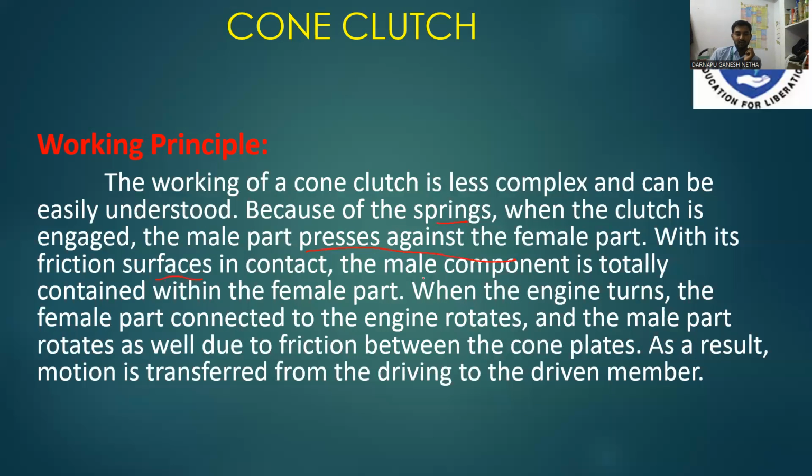When the engine turns, the female part connected to the engine rotates, and the male portion rotates as well due to friction between the cone plates. As a result, motion is transferred from the driving shaft to the driven shaft.